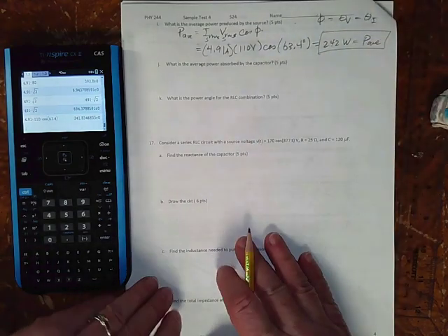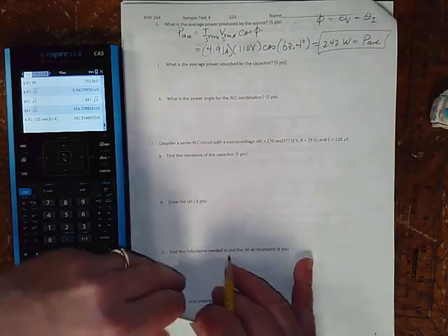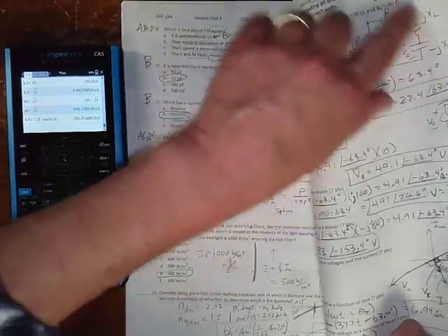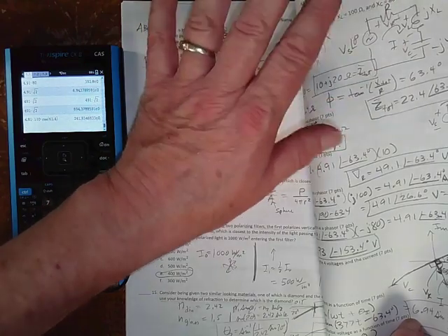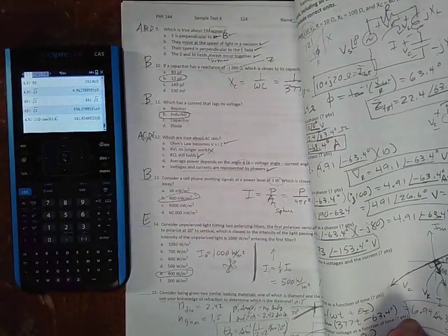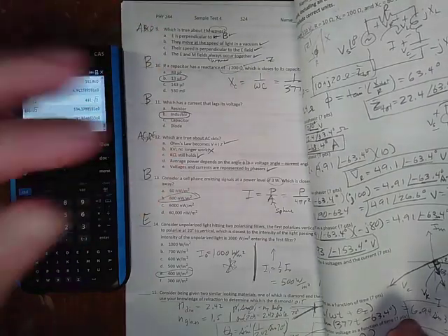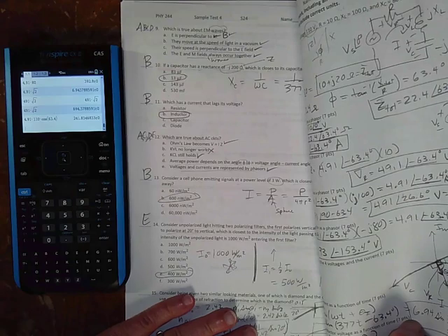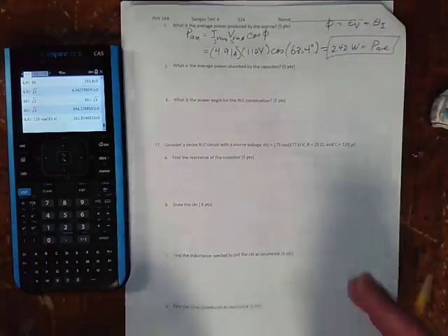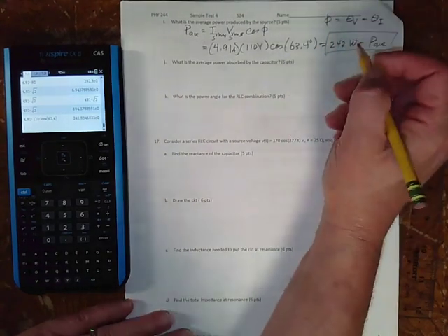Since in our circuit, we know that capacitors and inductors don't consume any real power or any average power. They have energy, they're passing it back and forth, but on average their power is zero. So the resistor is the only component that's taking real power, or average power, the only power that the source has to provide.